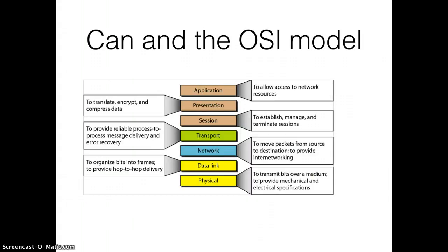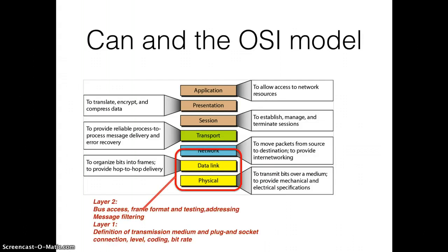If we look at the OSI model, that we have gone through previously, we have the 7 layers that you know. A CAN bus system, including controller and PHY as shown in one previous picture, implements layer 1 and layer 2 of the OSI model. Layer 1 is the physical layer, which needs an external transceiver that you have to work with in order to send on a bus.